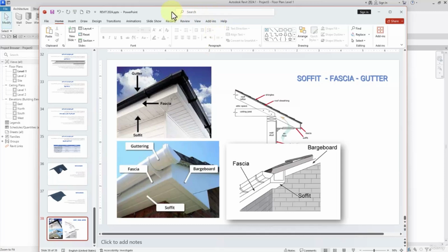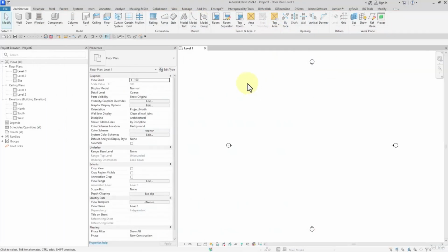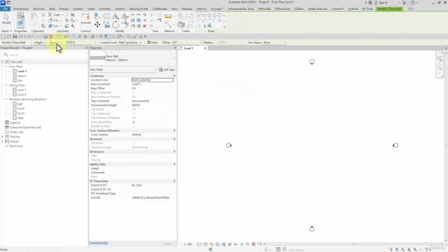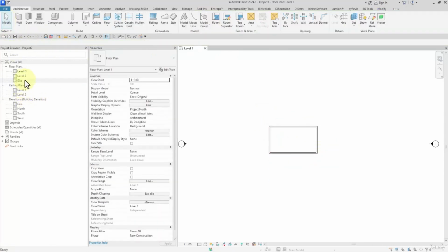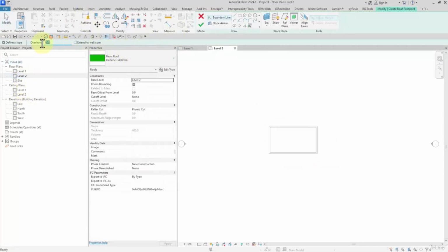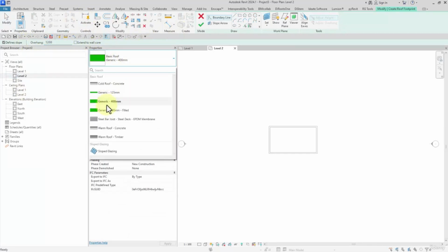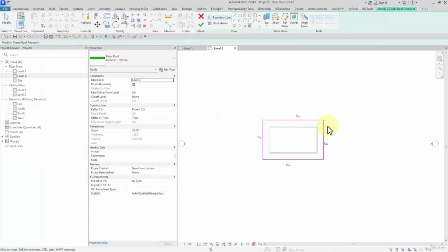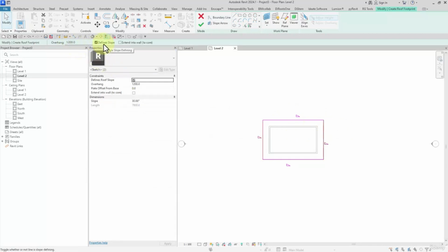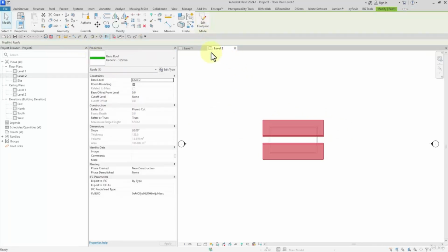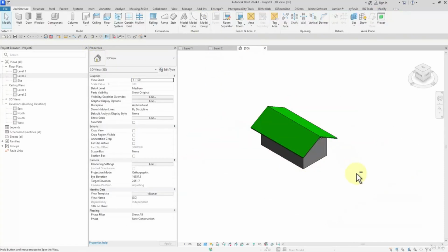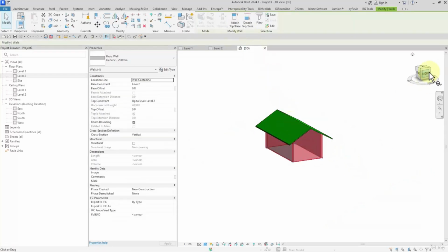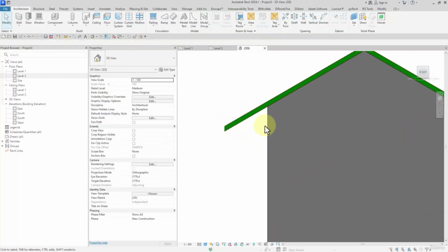So these three tools are being used for modeling the minor parts of the models. Again, we're gonna start from modeling walls, and then we open the level 2 using roof and defining the overhang 1 meter and 20 centimeters, and I undefine slope and finish. Here, as you can see, in this part, let me hide the level. If I attach the walls to the roof, as you can see, this part is empty that we want to fill it.